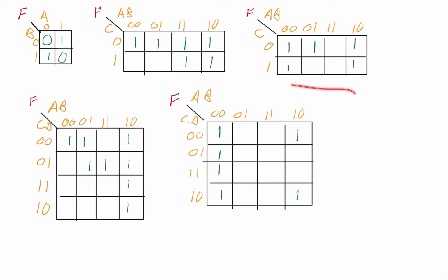Now I've drawn up quite a few examples of some K-maps so we can work through this. If you want, you can pause the video and work through it yourself and then come back and see if you got the right answer. A couple of notes: I just left all the zeros blank in these K-maps. So if there isn't anything in the square, then that means it's a 0. The other thing, this is a 2 input AND gate with just A and B, and this will still work because we still change just 1 bit moving side to side and only 1 bit moving up and down.